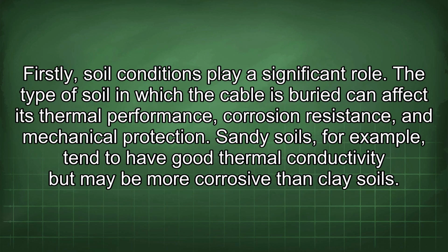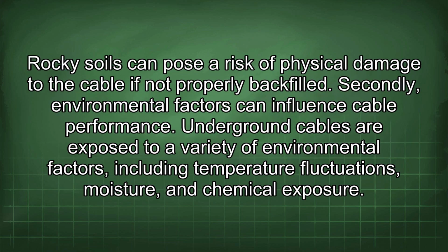Firstly, soil conditions play a significant role. The type of soil in which the cable is buried can affect its thermal performance, corrosion resistance, and mechanical protection. Sandy soils, for example, tend to have good thermal conductivity but may be more corrosive than clay soils. Rocky soils can pose a risk of physical damage to the cable if not properly backfilled.